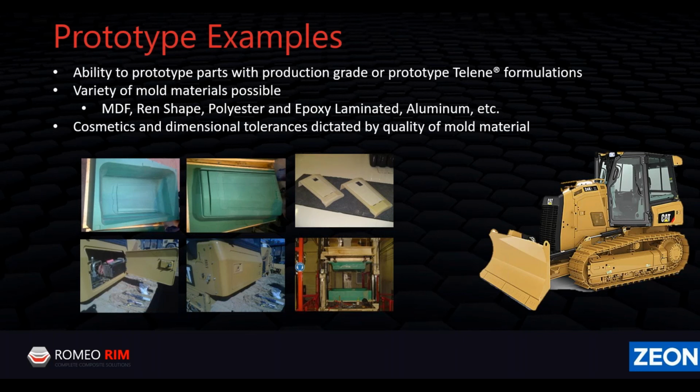Are you simply looking for a functional part? Does it need to have cosmetic appeal, for marketing evaluation and/or presentations and that sort of thing? But you can run anything from simple MDF, CNC machined MDF tools, wrench shape, up through polyester and epoxy laminated tools, and even to partially completed aluminum tools, depending on the number of parts that are required for prototyping, the cosmetic level, the complexity of the part